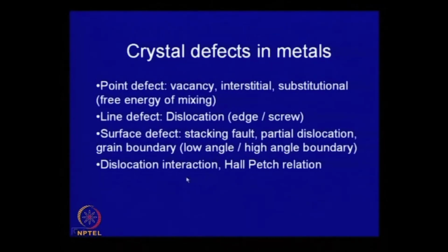We will also look at dislocation interactions and some of the dislocation mechanisms for strengthening. We will look at the Hall-Petch relationship, which defines the strength of metal as a function of its grain size.